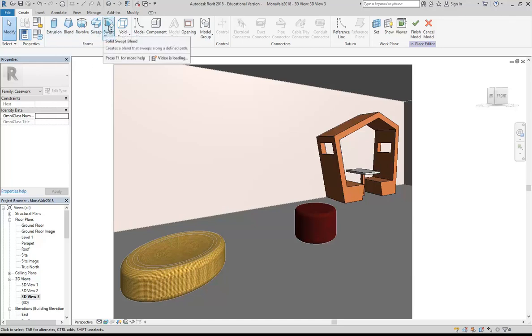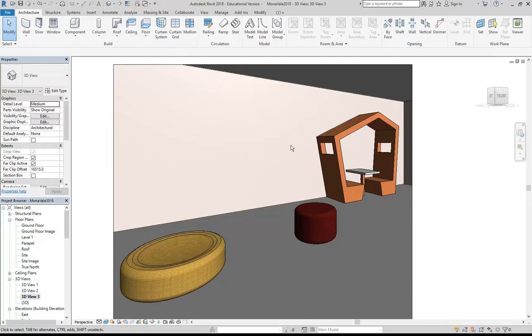And if you needed to add cushions to your wood, or is that a separate? Yeah, well, look, cushions can be tricky because cushions are an organic form. So that is one thing where I'd say, I normally don't say get it from a library that you've downloaded, but that's something I would usually just try and download. Oh yeah, if you just want to do a little circular cushion, you can model it. But if you want a proper cushion that looks like a tapering, nice soft cushion, you'll find them. If you search Revit City or even the library that we've got here, I've got a few cushions in there, and you can just place them and grab them from the library. They work really well.